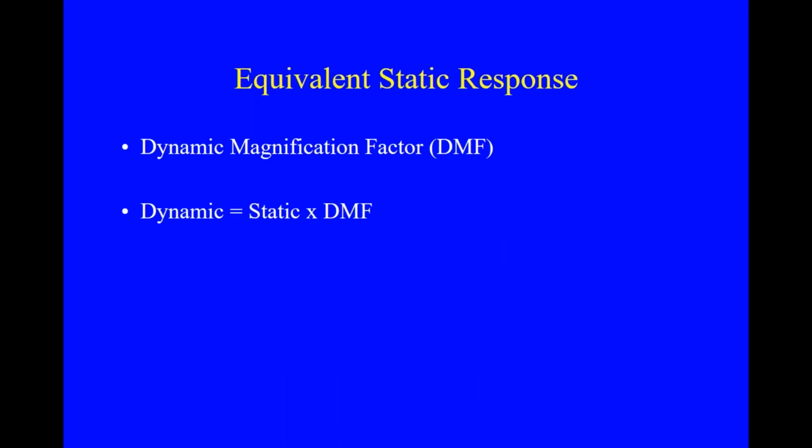If we take those equations and solve them, then what we've actually got is that the response equals force divided by stiffness for that static case. This is the laboratory test. We often do them on single beams, something like that. If we set the frequency to the resonance, then we've got response is the force divided by the stiffness, and then DMF, dynamic multiplication factor. That depends on the structure.